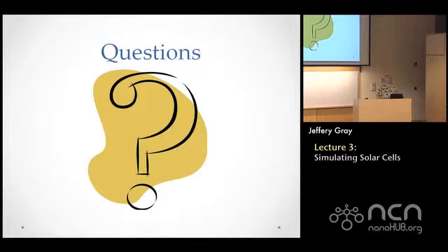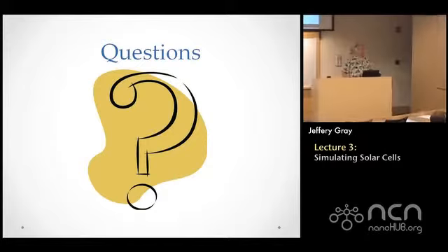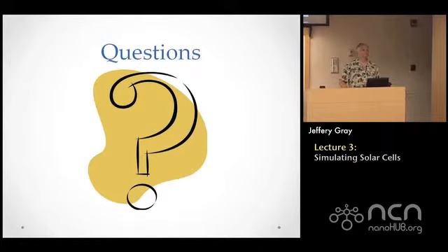For a multi-junction cell, it seems like just putting them in series is, you said something about if the short circuit currents don't match, then you have problems. I would see that could cause some cells to be sort of put into forward bias. So is that part of the optimization? Well, yeah. Picking the band gap, so that's perfect. But there's debate about that.